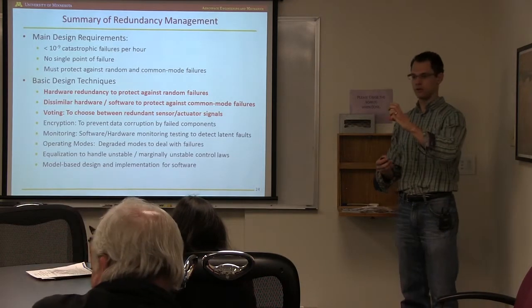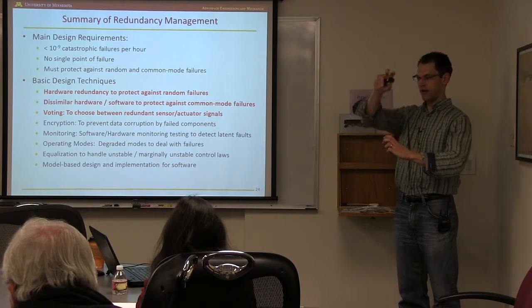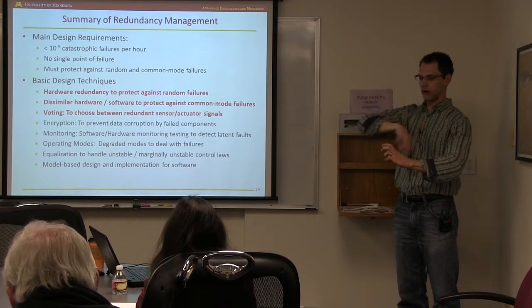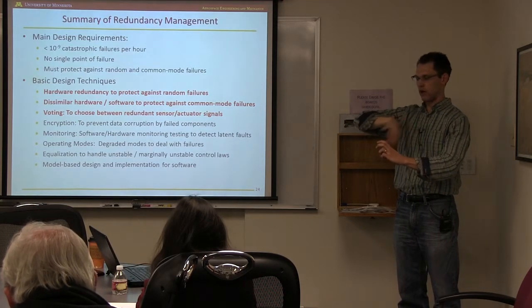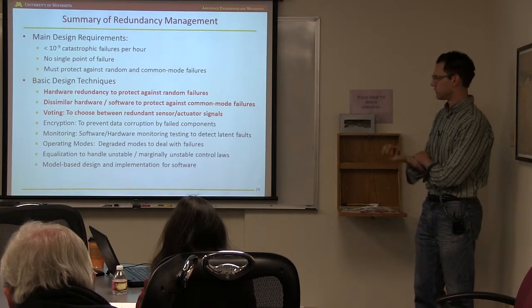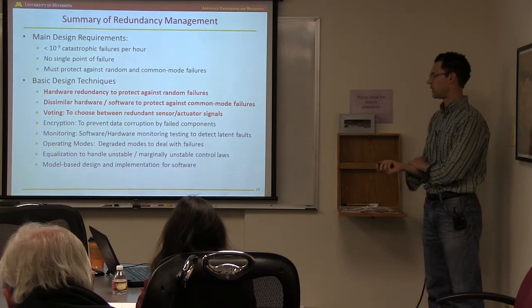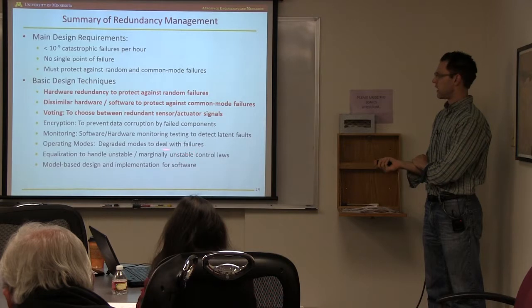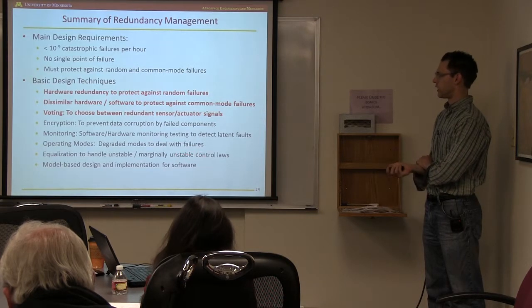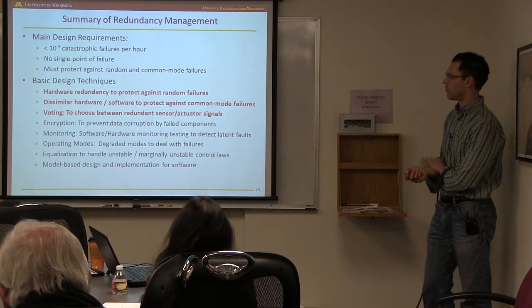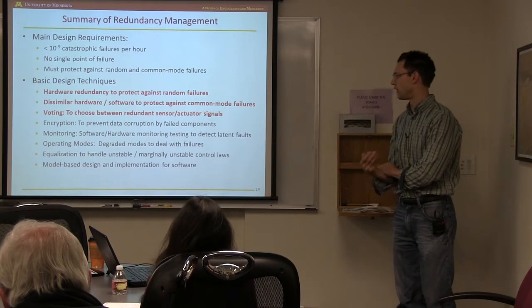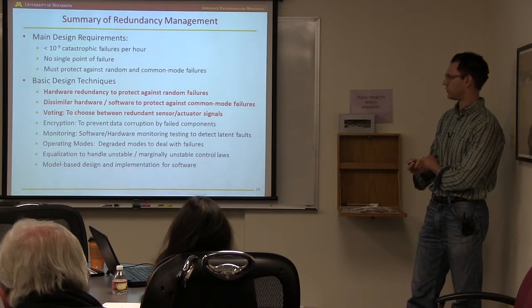Okay, imagine I've got an integral control, and it's not actually flying the plane. It's just sitting on a computer, kind of waiting off to the side. It's just running, waiting to run. And in some ways, this is what's happening on a commercial aircraft. You've got a marginally unstable controller and it's just kind of drifting off, and so you have to handle that in some way. So any sort of unstable control laws have to be handled in some special way.